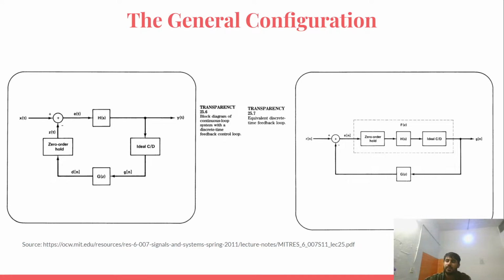Now, if we abstract away from the telescope positioning system, we here have a continuous time system, to which we want to apply some feedback, which we could do with a continuous time system or with a discrete time system by first converting these signals to discrete time signals, then processing that with the discrete time system, and then through the appropriate interpolation algorithm, we could convert that back to a continuous time signal, and the difference between this feedback signal and the input signal forms the excitation to the system that we are trying to control.